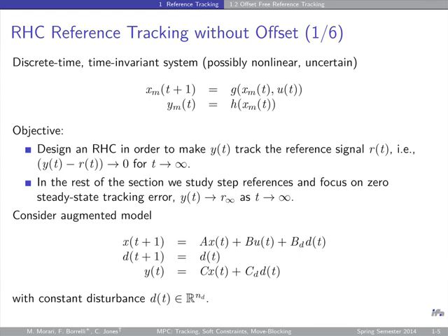So I have now one more equation. This was the standard equation. This is my augmented equation. Remember, this is what I added to the system of equations. So I have the system equation plus this, and accordingly this initial state for X and D. Otherwise it's the same MPC, but in addition I have this equation that I need to solve when I have this, let's say, quadratic program. I solve the quadratic program subject to those equality constraints, etc. But it's basically again a quadratic program.